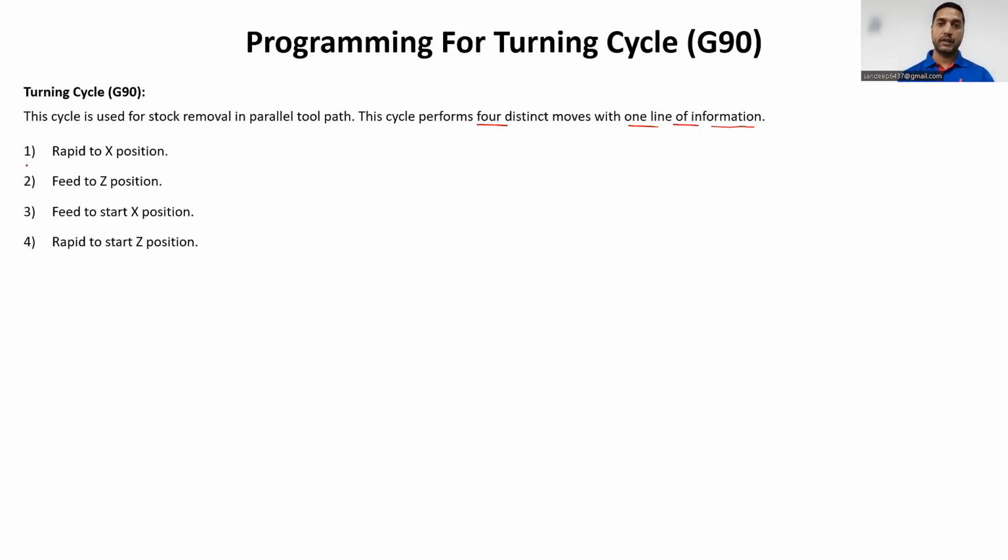The first move which it will execute is rapid to X position. Second is feed to Z position. Third is feed to start X position. And the fourth move which it will execute is rapid to start Z position.